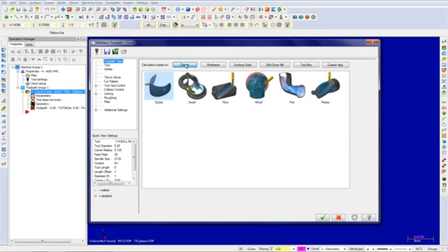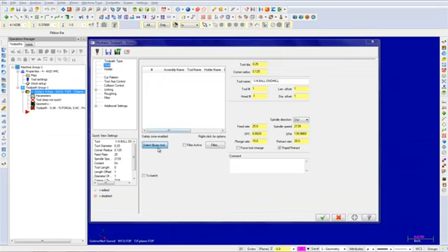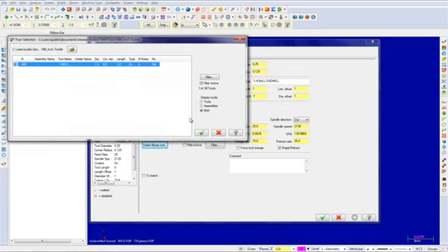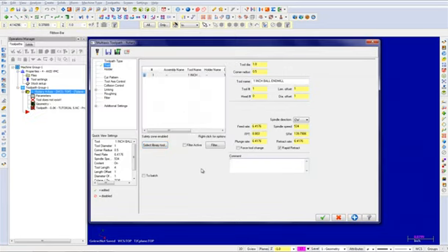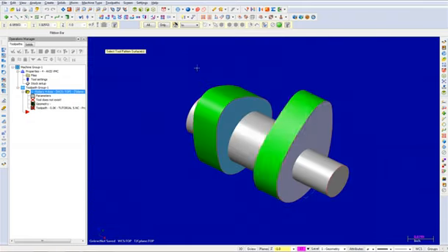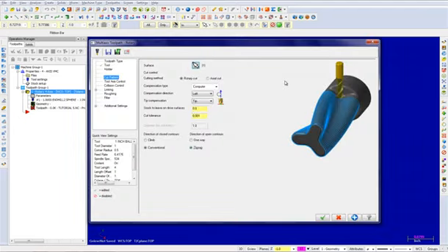In the classic view, choose the rotary type toolpath. Then select Tool. Click on Select Library Tool and find a 1-inch ball end mill. Then enter in a comment. Choose Cut Pattern. Click on the Select button here and choose this surface. Then click on the End Selection button up here.